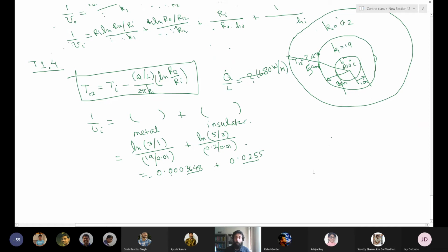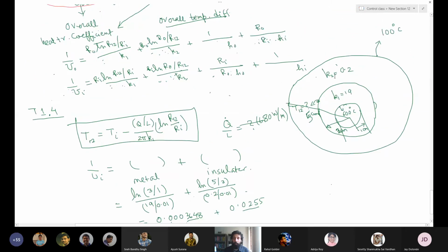Okay. Now this schematic itself shows an interesting feature of this cylindrical system. That is called the optimum thickness of insulation. If you increase the insulation thickness, of course the heat has to travel more distance, but at the same time you see the heat transfer area is increased. The area from which the heat is transferred is increased.